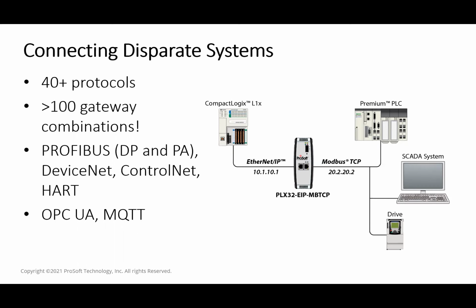That means you've got all of these different types of industrial languages or protocols at all of these different sites that need connection. It is not feasible to have a top end to monitor all of your systems that, let's say, only work on Ethernet IP, and another one that only works on Profibus. That's not economically possible. You're not going to have a clean overview of the entire system. So the ability to connect these disparate protocols and then have this information available in a single common top end is very, very important.